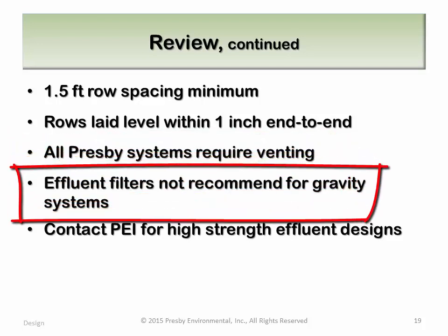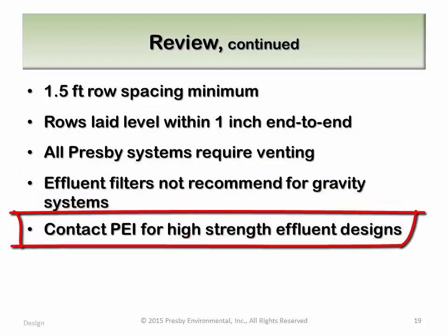Effluent filters are very popular. However, they are not recommended for use with gravity-fed Presby systems because they tend to inhibit airflow through the field. When you're designing for high-strength effluent applications, contact our technical support team for sizing recommendations. Remember, our technical support is always free.